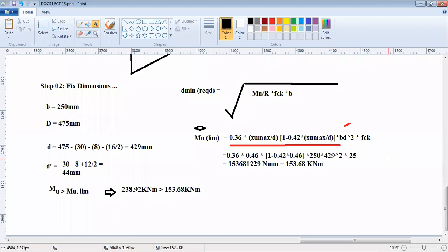What you realize is that with the increase in the design mix, you have to go with a decrease in the water cement ratio, and you have to go with an increase in the cement content. So there may be a limitation to that. And then with the increase in the FCK, you require admixtures. You do not want to include admixtures or superplasticizers for workability purposes. You do not want to include them. So there is a limit to FCK as well.